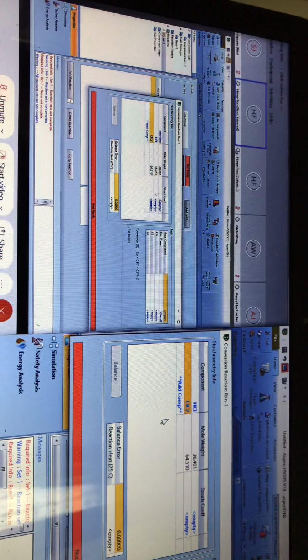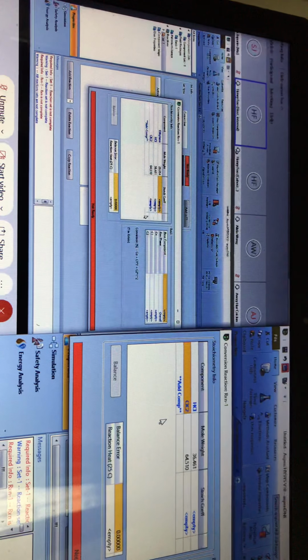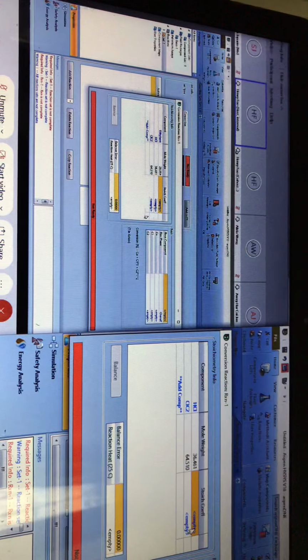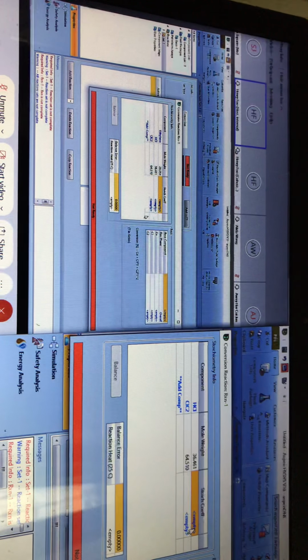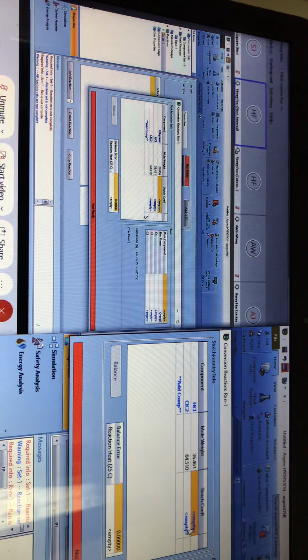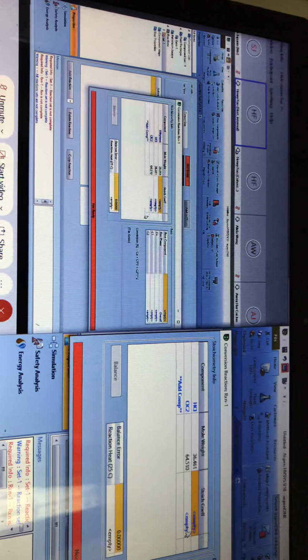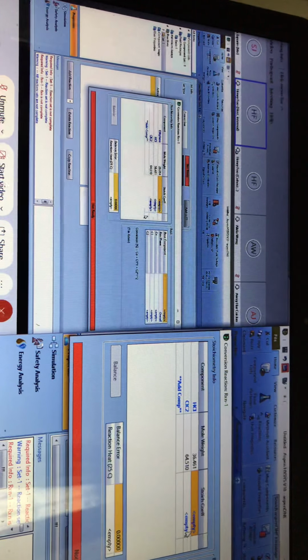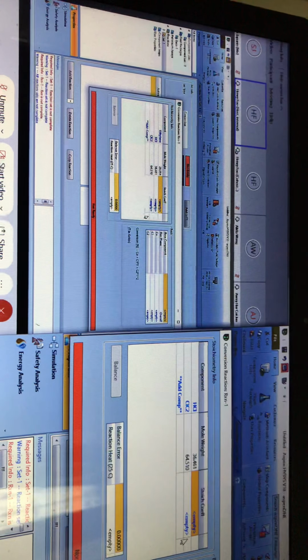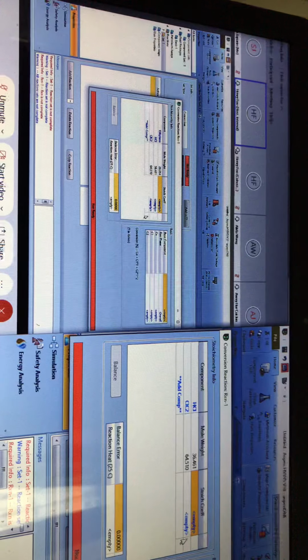Okay. So once you select the component axis in your reactions, next you have to define the stoichiometric coefficients. Basically, they are the coefficients of the stoichiometric reaction. In this case, you have to be careful with the sign, either negative or positive. If it's a reactant, then we should put a negative sign. If it's a product, then we need to put a positive sign.